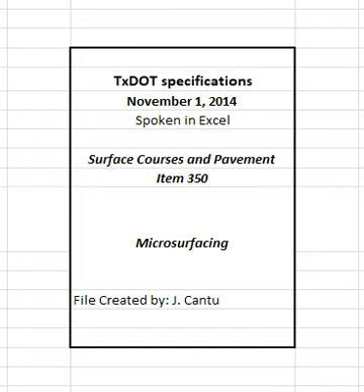5.2 Polymer modified asphalt emulsion. The quantity of polymer modified asphalt emulsion in the accepted portion of work will be measured by the ton of material based on the accepted load tickets issued from the manufacturer. At the completion of the project, any unused emulsion will be weighed back and deducted from the accepted asphalt emulsion quantity delivered.